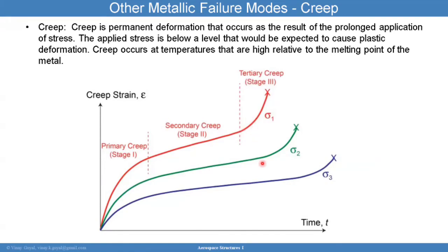Temperature also has the effect of increasing the creep rate, and so you can use that fact to accelerate life testing by, say, for example, I want to test a part under 10,000 psi, and I have to test it over 1 year. Well, that's going to be a long time to test that. You could then increase the temperature and test it to then accelerate the test program and still give you the curves you need for design.